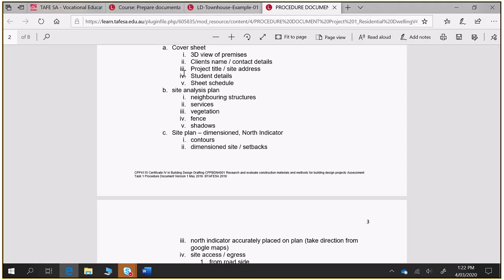Council are going to want to see, and I apologise for those watching this at home, so we've got three allotments there, we've got a house here, your house there, like that. Council are going to look at this, and if your house is back here, they might say no. Why can't we keep frontage or front distance more than whatever is on the neighbour side? Well, it is a grey area, and I just made a really simple representation of that. But let's say minimum setback is 10 metres, and both of these places comply with that minimum setback of 10 metres. And you can say, well, it's a minimum setback, I can set mine back further.